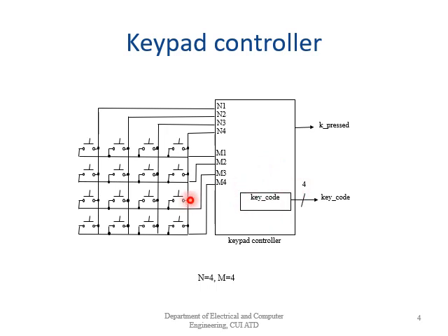Our software may poll this after every 100 milliseconds rather than checking the keypad pin to see whether it is high or not and then checking the code. What our processor software can do is poll after 100 milliseconds.